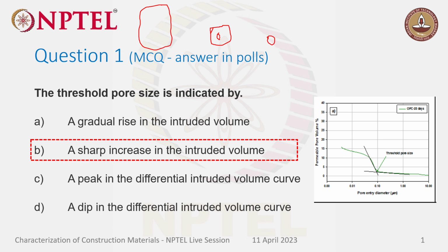So when it comes to MIP also, if you have some doubt, it should be the same. If you take samples from the core, and say you're taking four different samples, say you take OPC cement, slag cement and fly ash cement mortar cubes, then you can compare how OPC differs from slag and fly ash. Whatever results you get from here is the representation of what you interpret from the technique you use. It may not be the true representation, but you are interpreting something out of the technique you do.